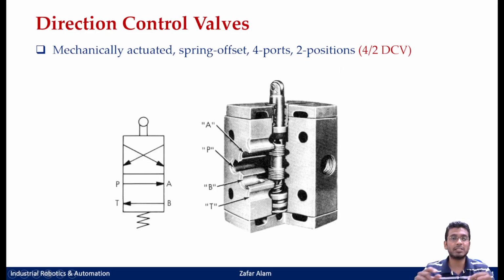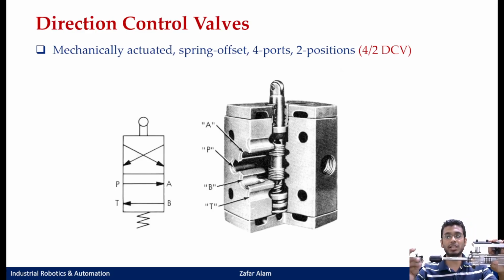That means if my cylinder is extending, say if this is my cylinder and it is extending, it actually comes and touches my roller valve here. Initially this is my roller valve which can get actuated like this. This will be fixed in one position. When this cylinder extends, it would come and touch this valve and close it. It would just press this like this, and it would engage this valve.